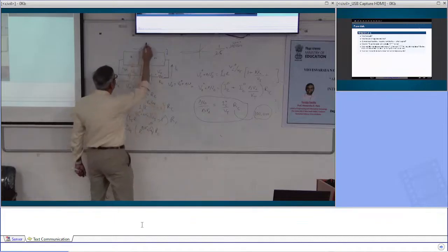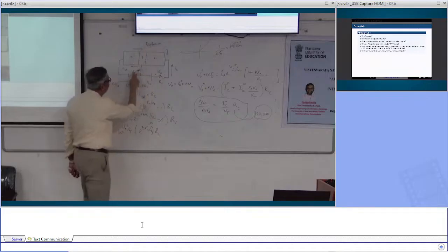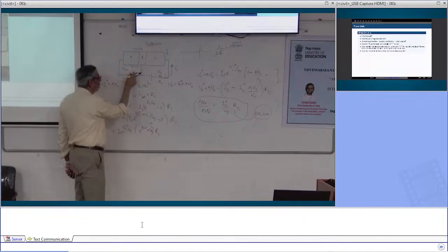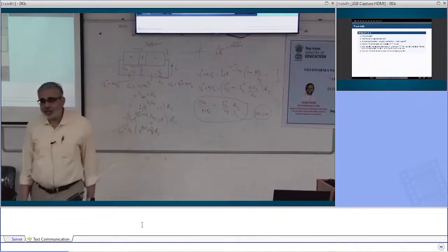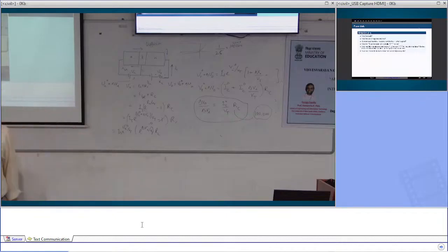And this is because of the principle of diffusion. Whatever the current, small voltage, this is forward bias. So by a very small change in this voltage, I can effect large changes in this current. And those large changes show up across RC. And when they show up across RC, they generate huge voltage, depending on the value of RC.